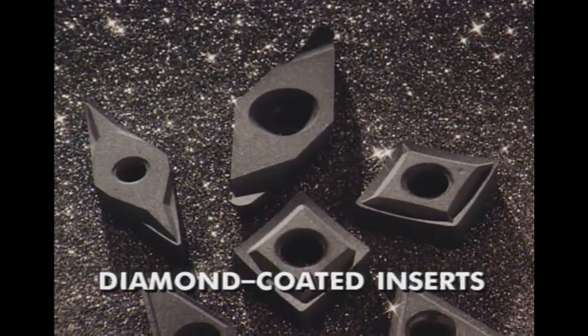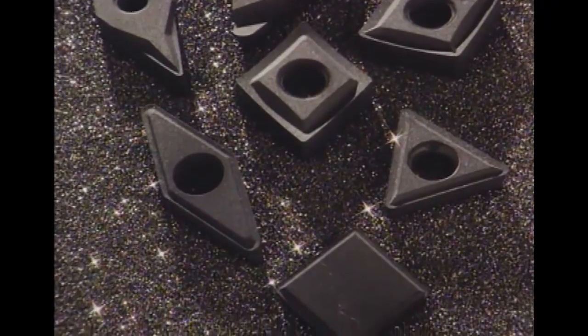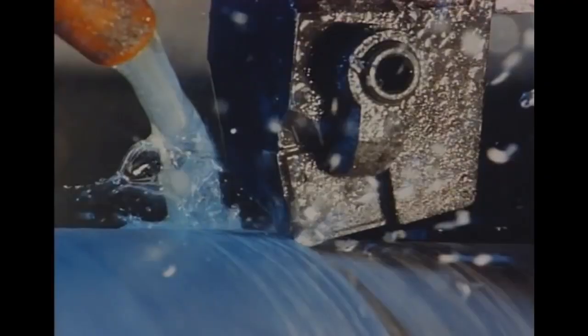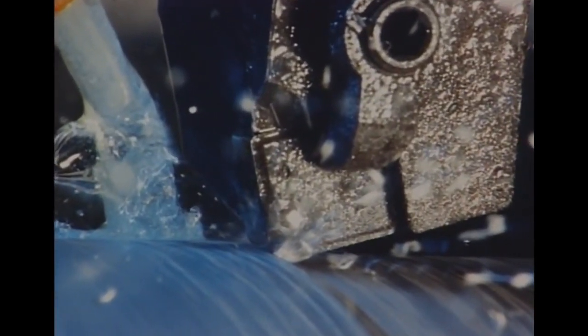Diamond-coated carbide and ceramic inserts are a recent addition to cutting tool materials. They offer a greater variation in geometries than do PCD inserts, but like PCD, can only be used for machining non-ferrous materials.